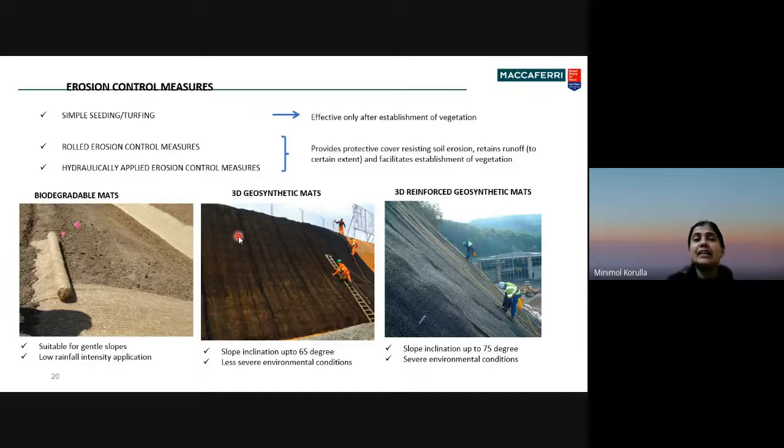But apart from that, I talked about there being different types of erosion control mat, and when the steepness of the slope increases, we may have to use an erosion control mat with higher tensile strength. The same polypropylene mat, if we insert a higher grade geogrid, which has 10 kilonewton per meter or 8 kilonewton per meter, will make the whole work a performing one, and there will not be any sudden collapse or failure.